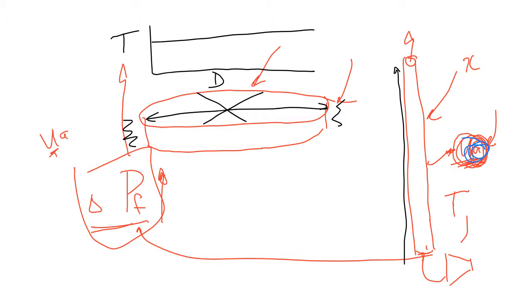This one has a very short tube diameter. I assume that I don't have any radial temperature differences, which implies that the temperature is constant even in the middle. The heat transfer is fast enough. Let's say I've got a very exothermic reaction that just wants to heat up more, and at the sides I've got my coolant that can cool it down.